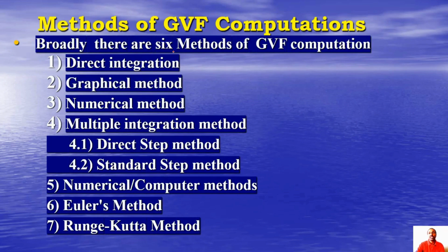These are the methods of GVF computation. Broadly, there are six methods. The first one is direct integration, where we integrate and calculate the length of backwater. Second is the graphical method, where we take some distance dx and then calculate. Third is the numerical method, and also the multiple integration method, which is also important. We have the direct step method and the standard step method.